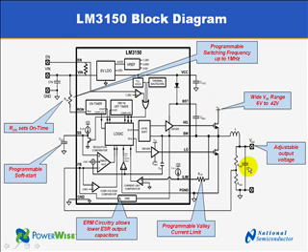The actual voltage of the output capacitor is determined by the duty cycle of the high side and the low side MOSFET. The output voltage is sensed by the resistive divider and is fed into the error comparator. It is compared to the internal voltage reference. From there, the result is fed into the logic circuitry, and this controls the duty cycle of the low side and the high side MOSFET driver.